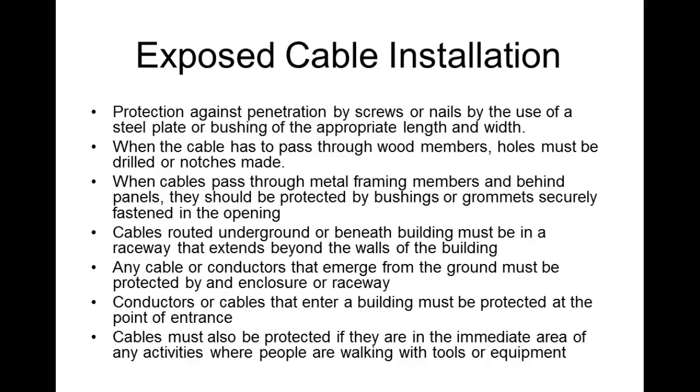A lot of times in residential wiring, we run the wire through the 2x4s in the wall. And people will come in there nailing up sheetrock and all kinds of stuff, and they'll nail into the wire, right? You understand that? They don't nail straight, and they'll come out the side and get into our wiring.